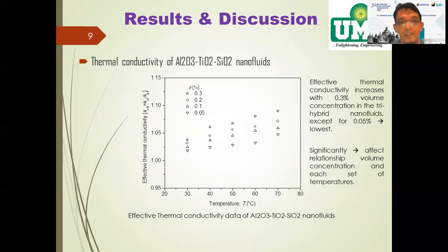And this figure shows the results of my experiment using KD2 Pro. Effective thermal conductivity increased with volume concentration up to 0.3%, while at 0.05% the increase is very, very low. So we can see a significant relationship between volume concentration and the set of temperatures.